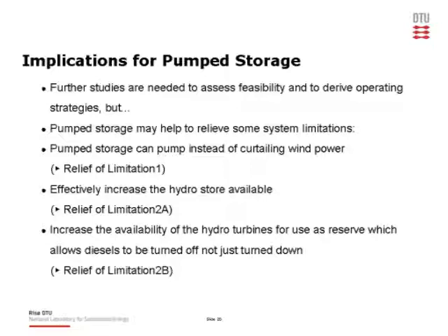And this is where you really save. If you can actually turn a diesel off, you will save a lot more in fuel than just by down regulating it. And that's because of the minimum fuel consumption that a diesel engine has. And this helps to relieve the second limitation of the hydro turbines.